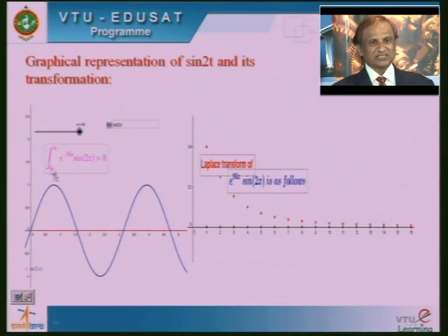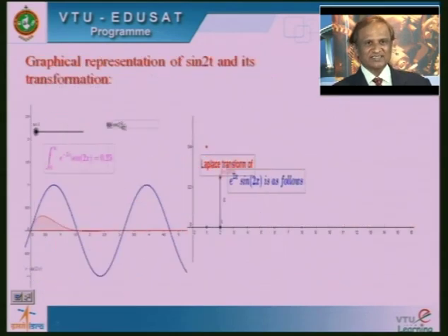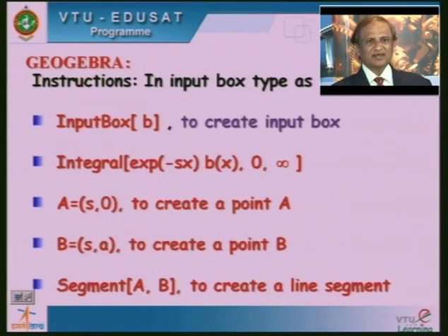So, you can use a software namely GeoGebra. Simply you want to type 4 or 5 commands in the input bar. I am going to show you those commands. Say for example, in the input bar in GeoGebra, you can type a command like this, input box, is it clear. So, this will create a box like this. In that box we can type any function, and after that, we want to integrate, so for that reason you can type integral exp minus s into x.